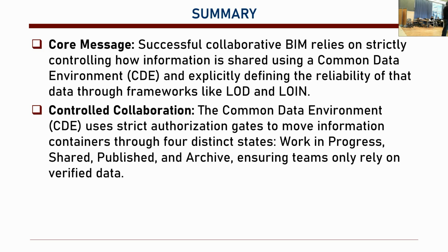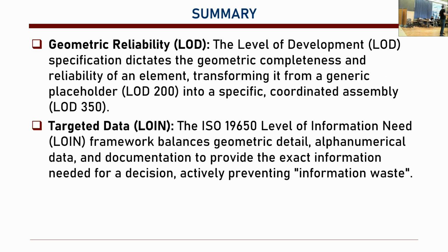You should tell them exactly what you want for each element. Then they put the right thing at the right time. See, otherwise CDE will not work. One person's acceptance for detail, other person's may not be. Okay, so you want to know how well they have defined. And for that, in the common data environment, we have a controlled collaboration. Basically, we have these 4 stages: work in progress, shared, published, and archived. And the teams rely on verified data. Teams have access control. Okay?